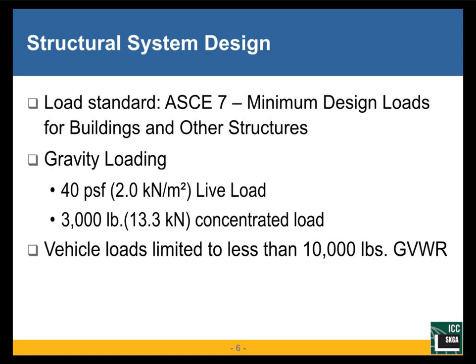But considering that the vehicle range that limits the design of parking structures to ordinary parking structure loads is 10,000 pound gross vehicular weight rating, and the consideration of the conservatism that was originally undertaken, that's not an immediate concern.